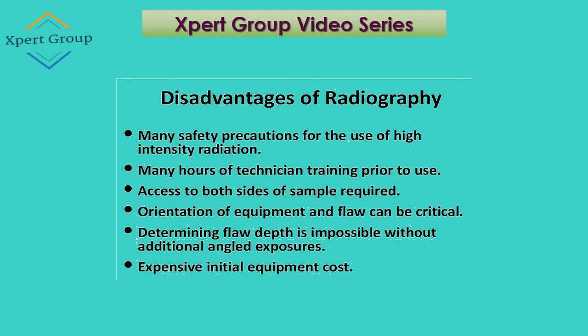Determining flaw depth is impossible without additional angular exposure. So this is another disadvantage of radiography: it cannot find out the actual depth of the flaw which you have found during the inspection. So this is a disadvantage related to radiography.